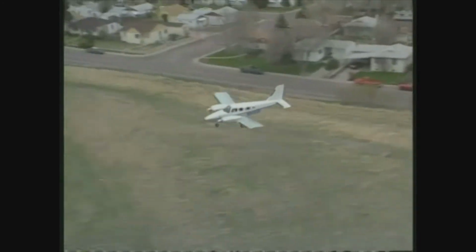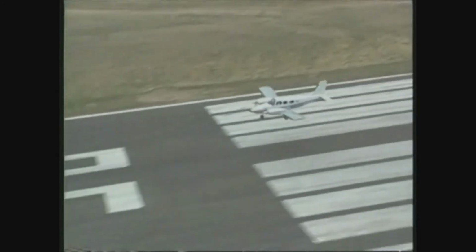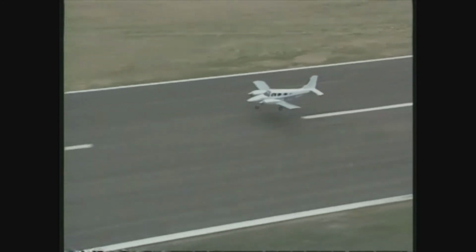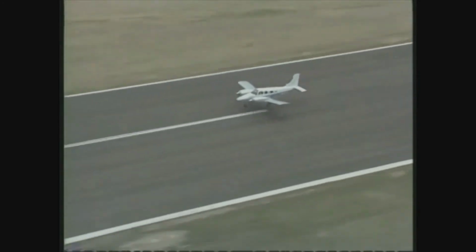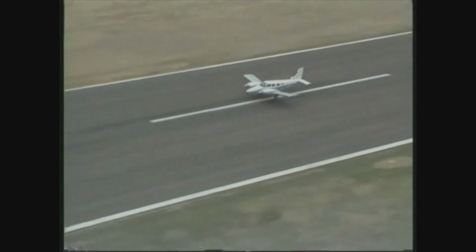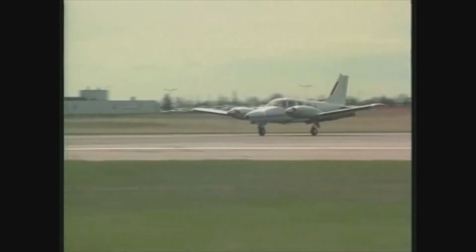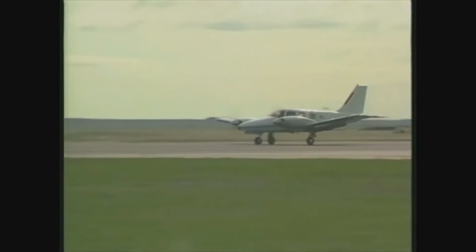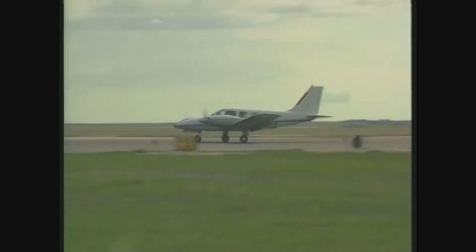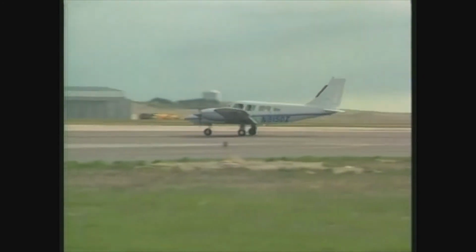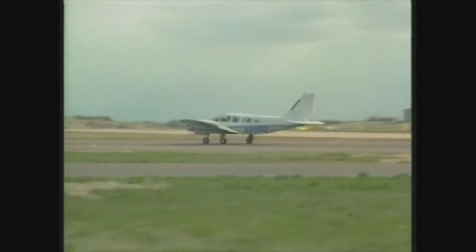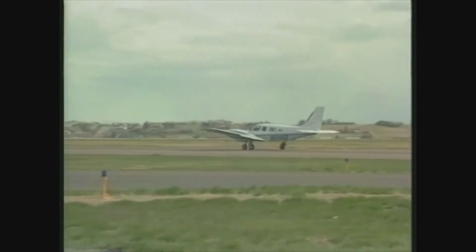As you approach the runway, make a smooth transition to the flare and slowly retard the throttles to idle. Remember that a rapid reduction in induced airflow will cause an immediate loss of lift. During the first part of the landing roll, use rudder and nose wheel steering for directional control. If runway and traffic conditions permit, avoid using the brakes until the airplane slows down.